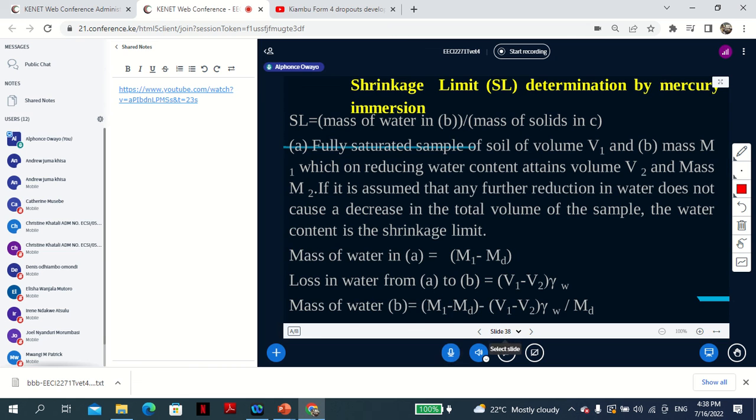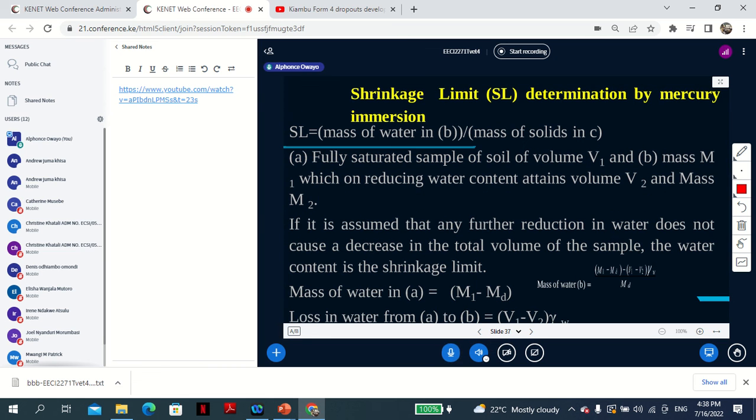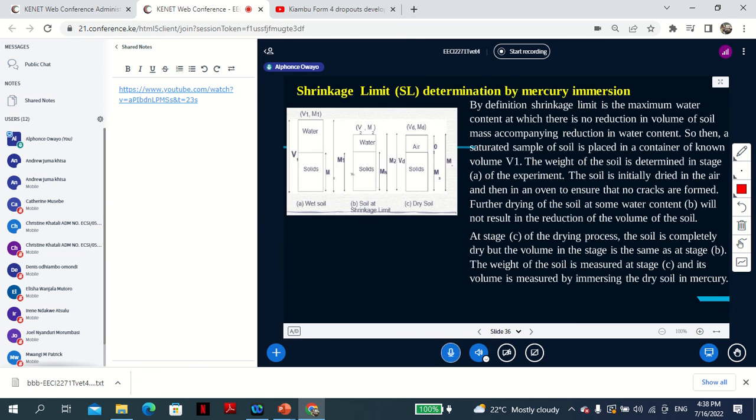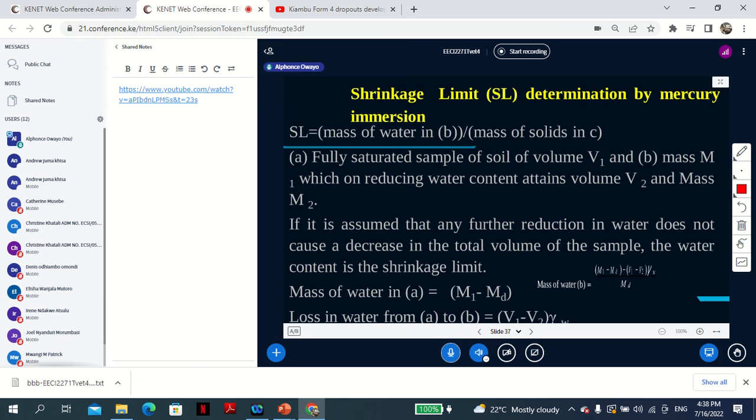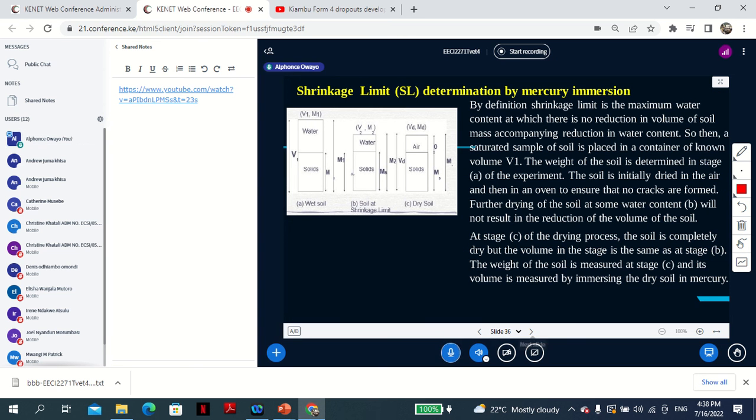I can see this in my experience with the road. When I was a student, I worked a little bit on road projects. I usually took samples in the evening or within the day, then left them in the oven and took results the following day. Now, this shrinkage limit will take you several days, even from the definition. That's why I'm saying it's a bit academic.